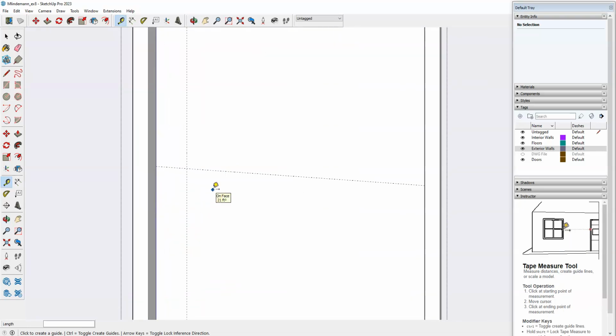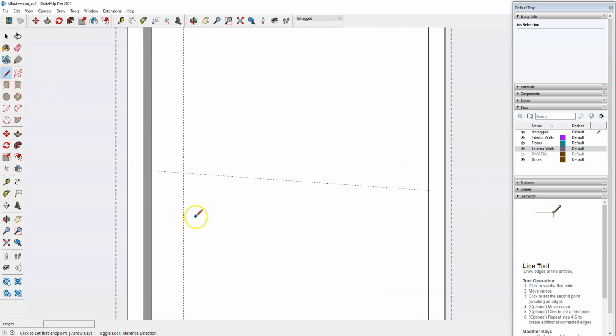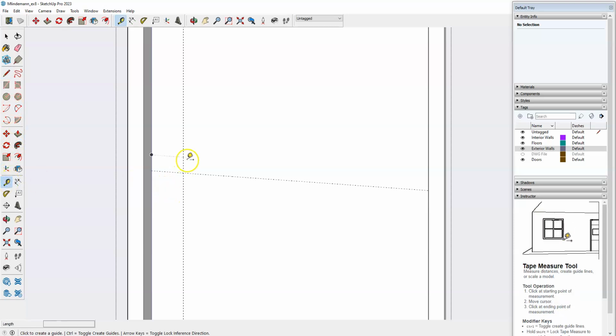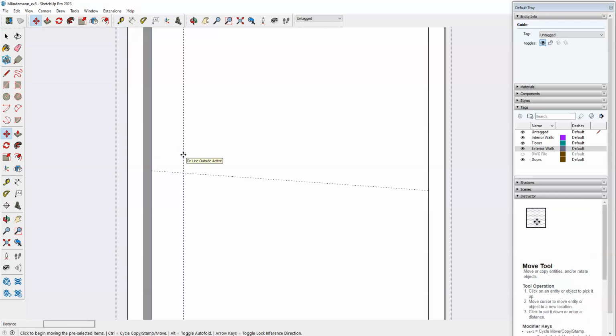So we wanted it 2 inches wide by 12 inches in height. We can either start right here in the center point and create it from here, or if it's easier for you, you can create more grid lines. I'm just going to copy this one 1 inch to each side of the center.